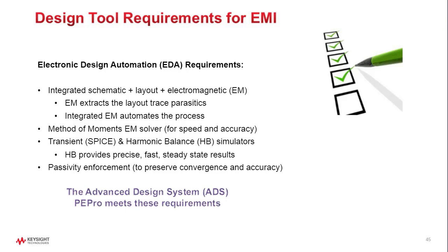In addition, the concept of passivity is important, and that is associated with S parameters and transient results that we run an analysis on, and maybe a measurement of electromagnetic analysis or S parameter measurement on a network analyzer. Sometimes the component results come back non-passive, and they might appear to be very, very slightly non-passive. Sometimes that's an issue with regard to calibration. There are other issues. We can address this issue, identify non-passive, and enforce passivity.